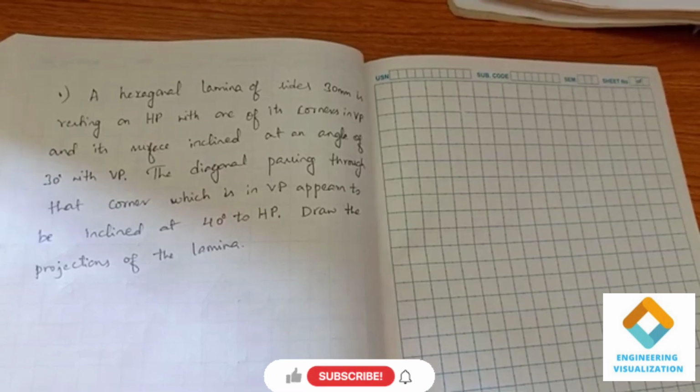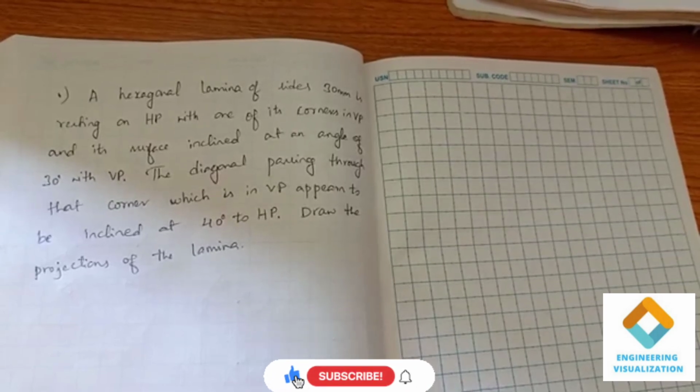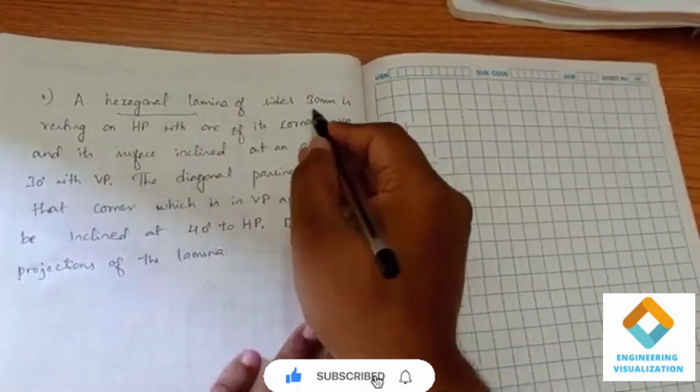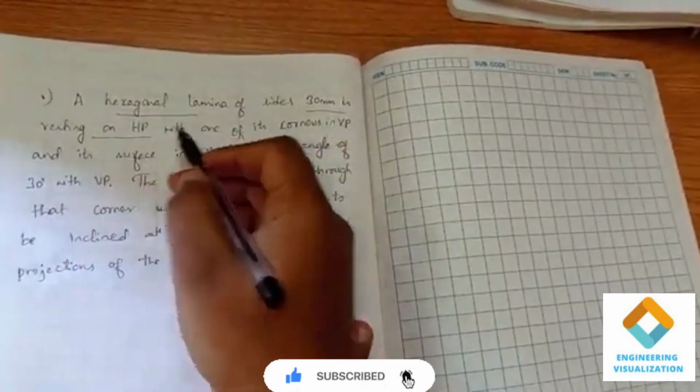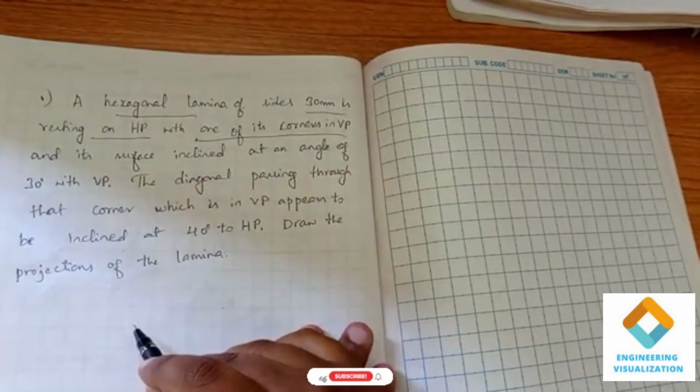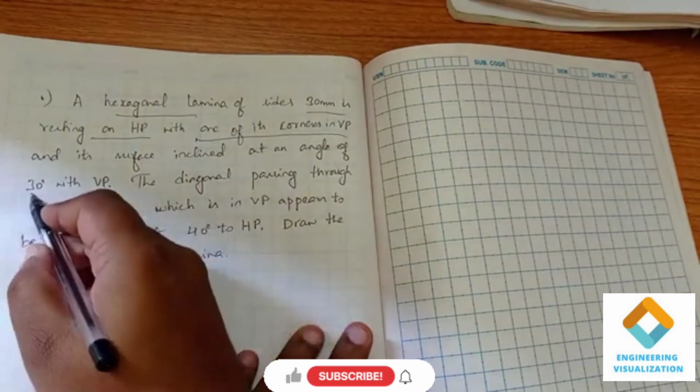We see a different type of problem in hexagonal lamina. In this problem we have to construct a hexagonal lamina of dimension 30, resting on HP with one of its corners in VP. It will be a different type, and the surface is inclined at an angle of 30 degrees to VP.